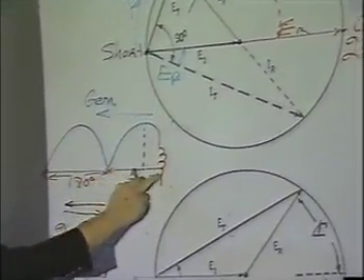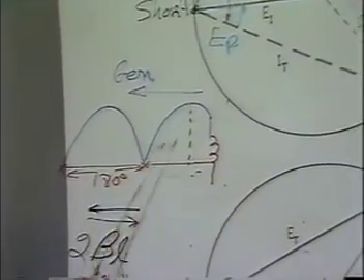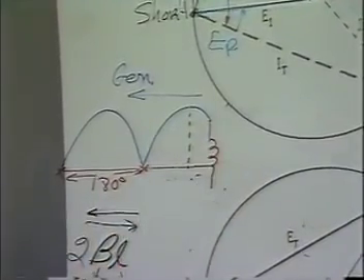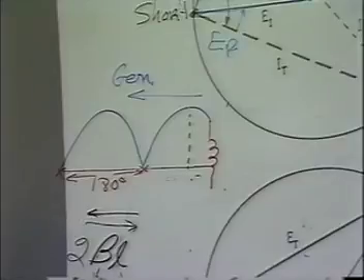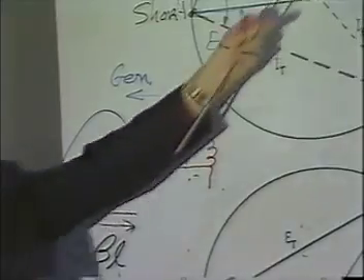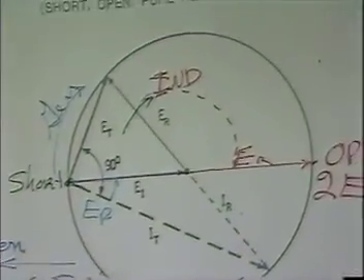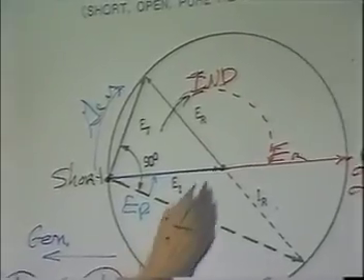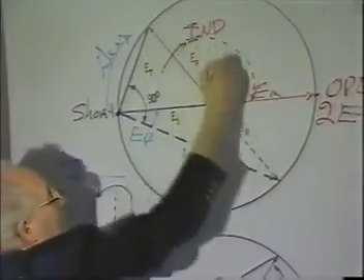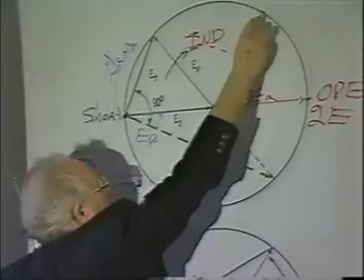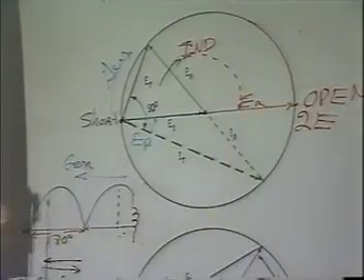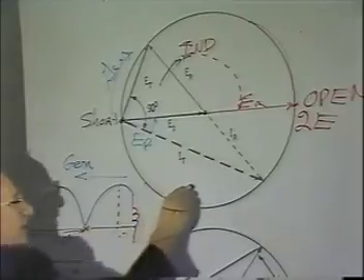Didn't change the minimum because I just changed the position and put an inductor in here and removed the other part of the line. So this inductance here is some value out here, isn't it? Now notice, I'll travel back toward the generator from some value of inductance up here, travel around here, and you'll hit 2E. That's a pure inductance. What are you going to have on the other side then?